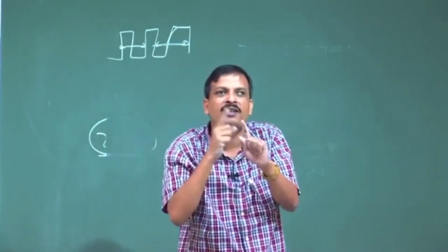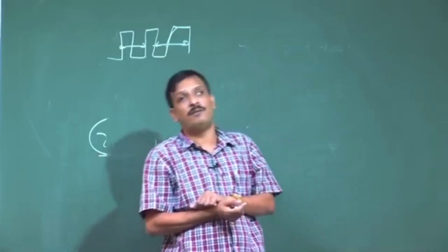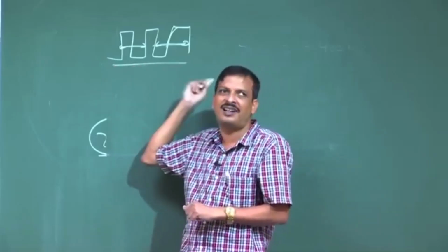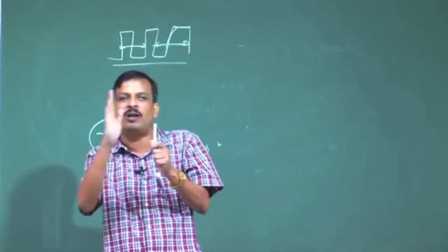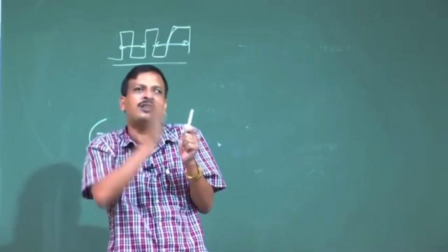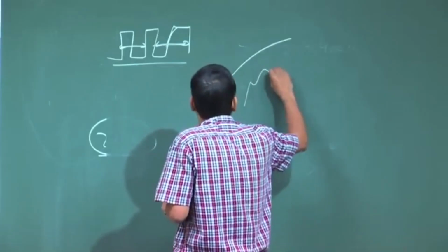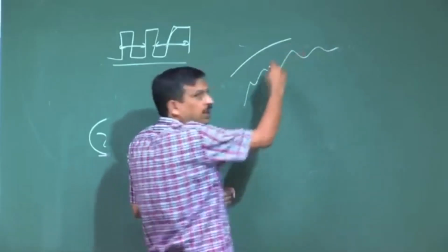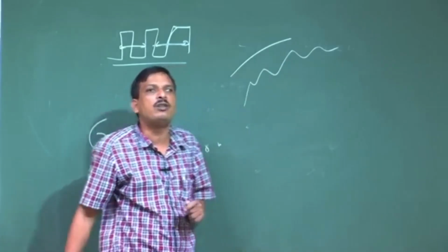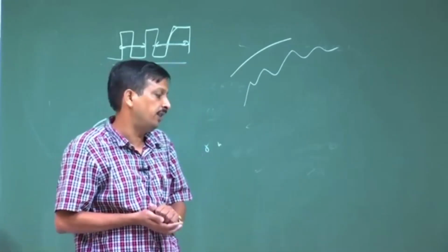There are some differences, and that small difference is called jitter. Suppose I have extracted an F0, I cannot say all the F0 values will be the same for some segment. The F0 is continuously moving, forward, backward, that kind of variation. So, it is not a smooth F0, it looks like this kind of F0 contour. Next period it is less, next period it is also; jitter is randomly varying, that is why it is called a quasi periodic signal, not an exactly periodic signal.